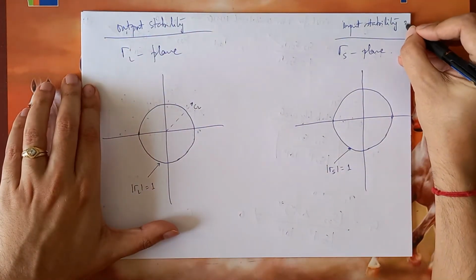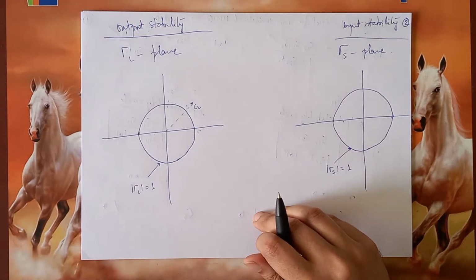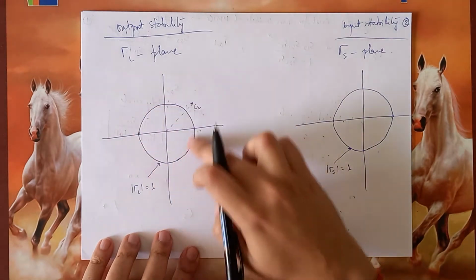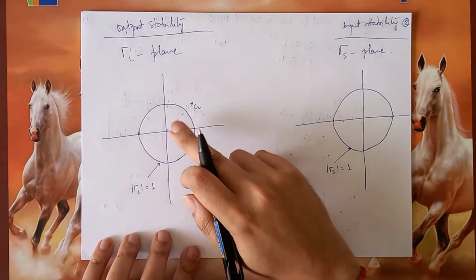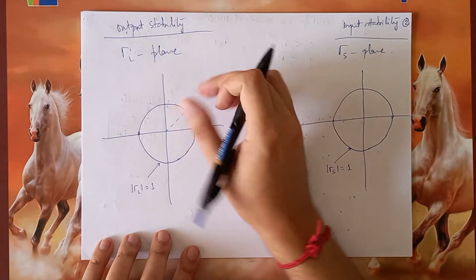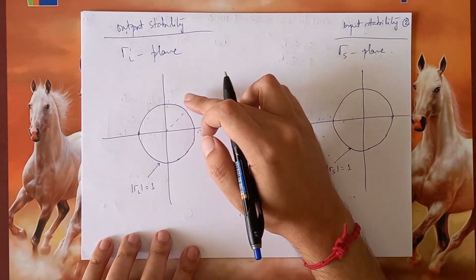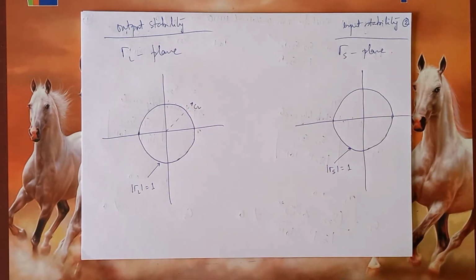Going by the discussion from the previous lecture, if S11 is less than 1, then any point in the Smith chart can be stable, or any value of ZL that you choose in the Smith chart can be stable. But if S11 in magnitude is more than 1, then ideally we choose the region of the circle that is overlapping with the Smith chart. Here that is not possible, so it can never be made stable.